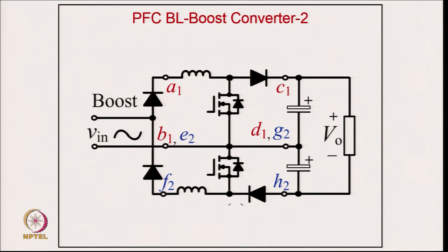Of course you have to use two devices, and this is the circuit for the positive half cycle and then the negative half cycle. But you can understand in some applications we require two equal voltages. Of course it is on load here, but sometimes you require two equal voltages with power factor correction, like a switched reluctance motor drive of 4 phase, where you require a midpoint, so that can give you a midpoint also for some applications, and so on.